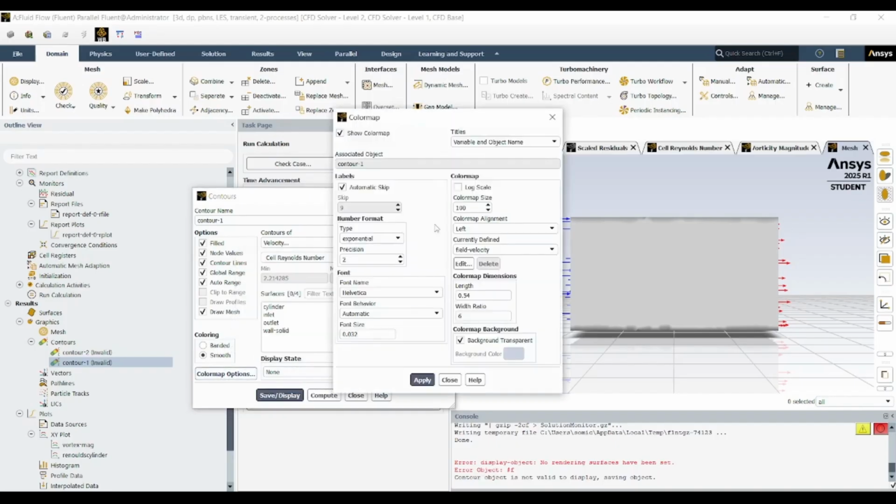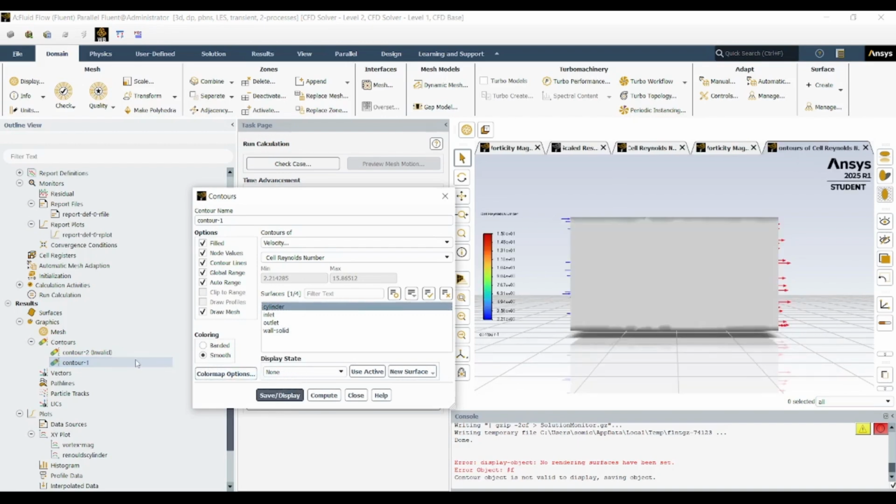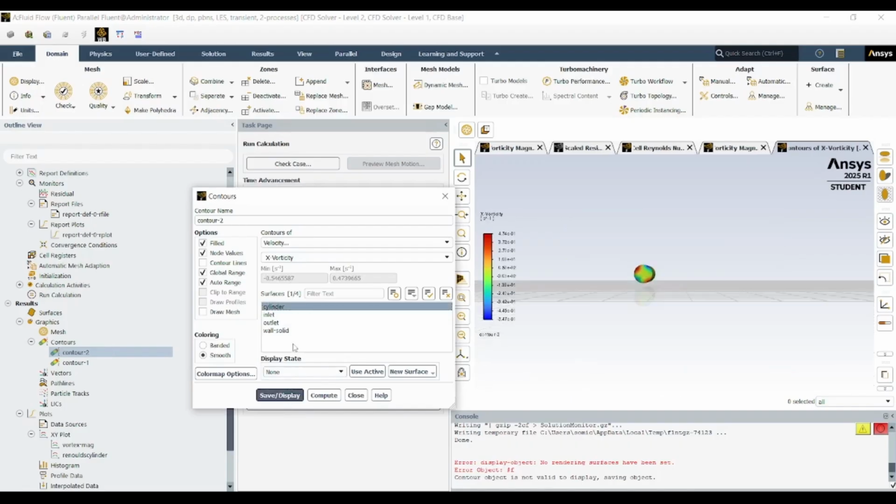As you increase the velocity, the flow transitions to unsteady vortex shedding, and at even higher velocities, the wake becomes turbulent and chaotic. This variation can be visualized through drag and lift coefficient plots, revealing how aerodynamic forces evolve with changing flow regimes. Performing such studies not only helps validate your simulation setup, but also strengthens your understanding of flow physics and the influence of viscosity, pressure, and inertia on bluff body aerodynamics.